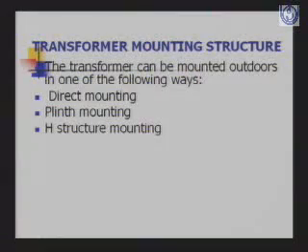The transformer can be mounted outdoors in one of the following ways. It can be direct mounting, plinth mounting, or edge structure mounting. Inside, of course, you are going to mount it on a plinth only, but outdoors you can use these three types of mounting for the distribution transformer.